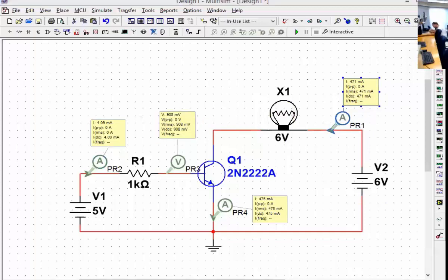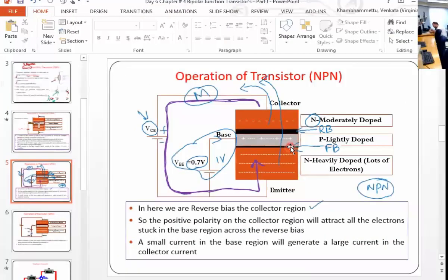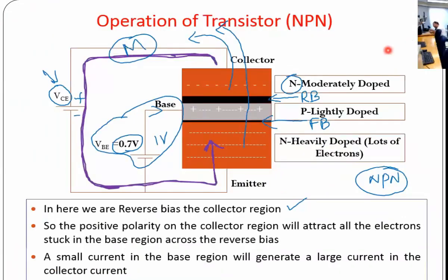Again, that's what this shows. That's an explanation too, of how that affects. So if you take a look at here, you have your base voltage, correct, which we call VBE. So that is the 0.7 which is applied. So that 0.7 will give us this current, right? Correct? See, this current right here is the current going through the base and the emitter, right?